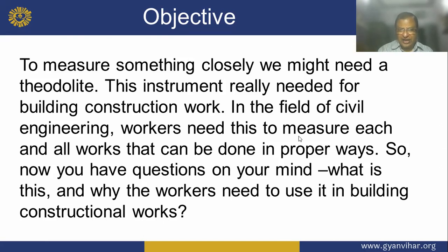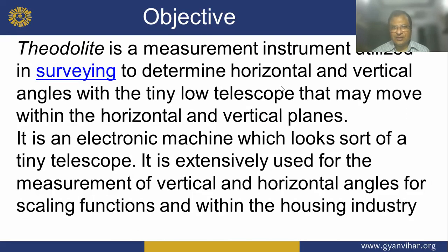So now you have a question in your mind: what is this, and why does a worker need to use it in building construction work? Dear boys, the theodolite is a measurement instrument utilized in surveying to determine horizontal and vertical angles between a point and a telescope that may move in the horizontal and vertical planes.